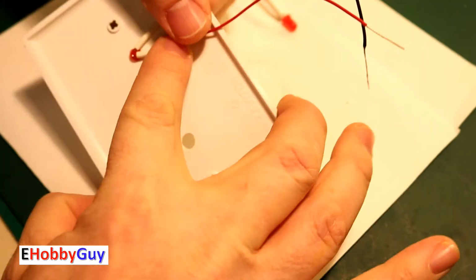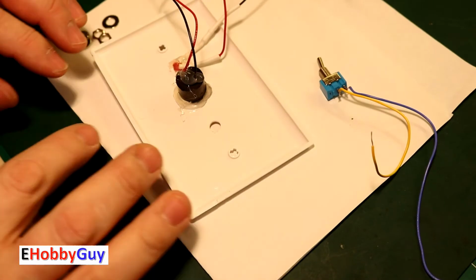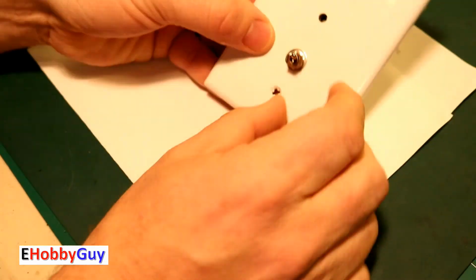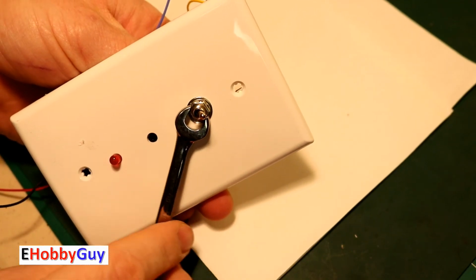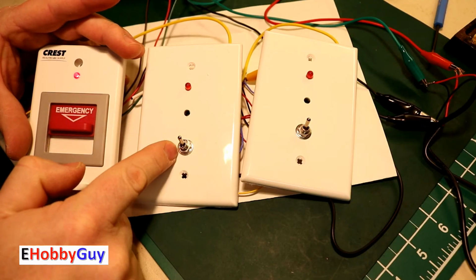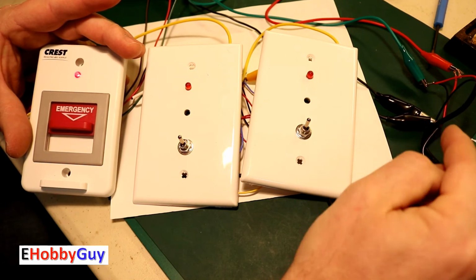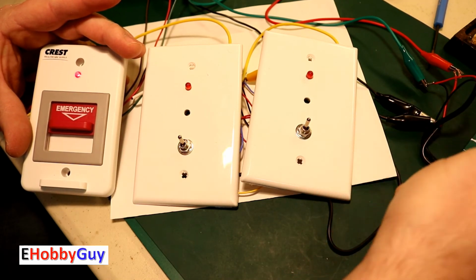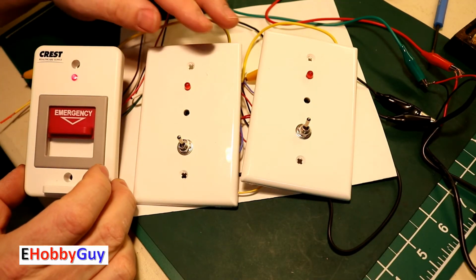And now it's time to mount the components, and so I just placed them in the holes and just used hot glue to hold them in place until all 6 components were firmly mounted. We've got the LED, buzzer, and the bypass switch on both. Over here I have the 12 and 24 volt, the center tap 12 here, 24 volt here, two negatives jumping everything together per the schematic.